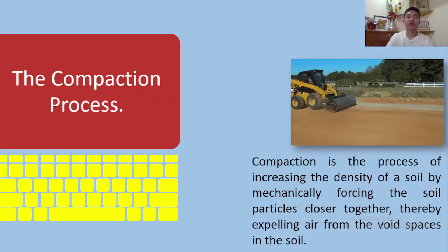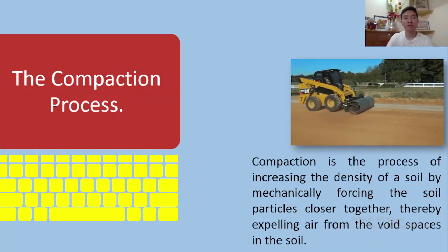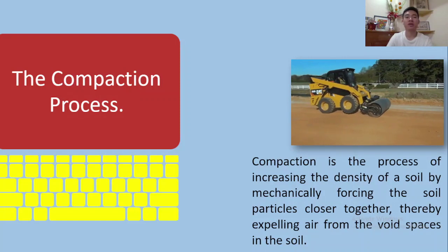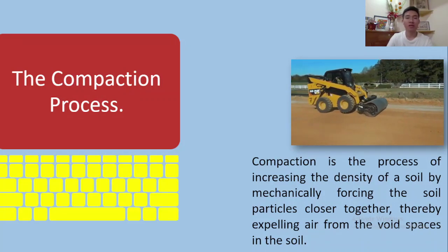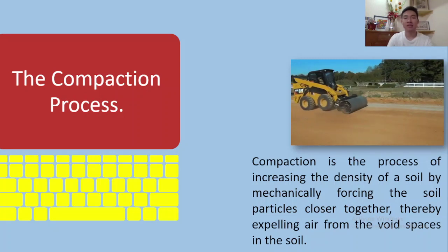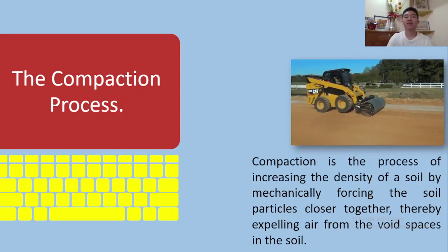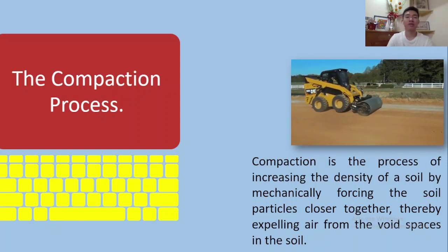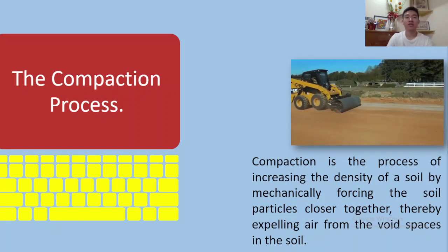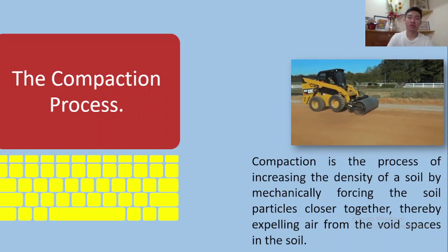In the construction of highway embankments, earth dams, and many other engineering structures, loose soils must be compacted to increase their unit weights, to compact a soil, that is, to place it in a dense state. The dense state is achieved through the reduction of air voids in the soil, with little or no reduction in the water content.